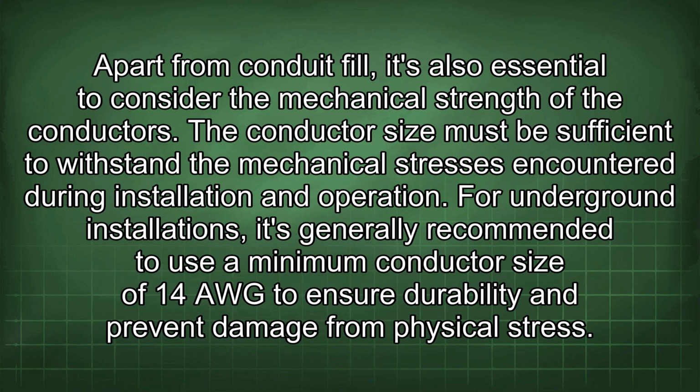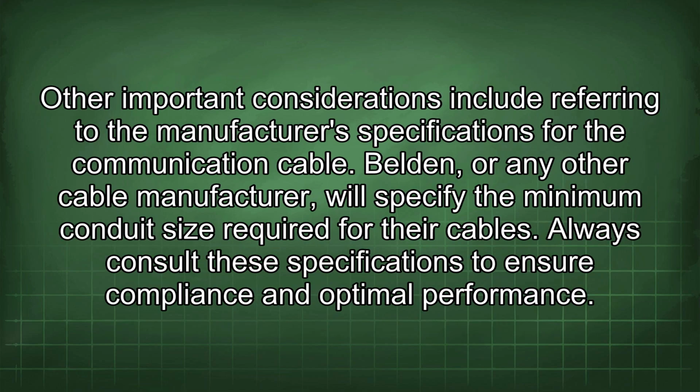Apart from conduit fill, it's also essential to consider the mechanical strength of the conductors. The conductor size must be sufficient to withstand the mechanical stresses encountered during installation and operation. For underground installations, it's generally recommended to use a minimum conductor size of 14 AWG to ensure durability and prevent damage from physical stress. Other important considerations include referring to the manufacturer's specifications for the communication cable.